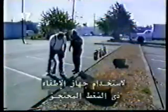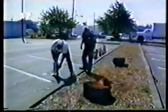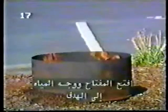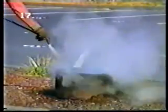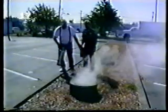AFFF stands for aqueous film forming foam. These extinguishers are used on Class A or Class B fires. They look like stored pressure water extinguishers, but the difference is that they have a concentrated foam agent as well as water in the tank. They also have a special nozzle that mixes air with the solution, making the discharge a foam instead of a liquid. These extinguishers are especially valuable for putting out liquid fuel fires.